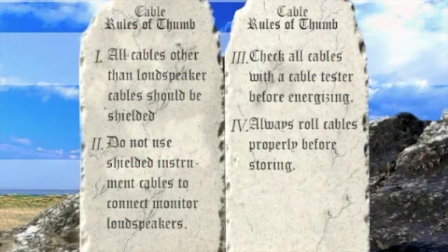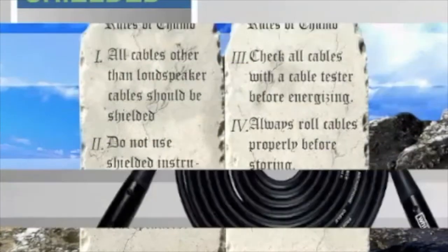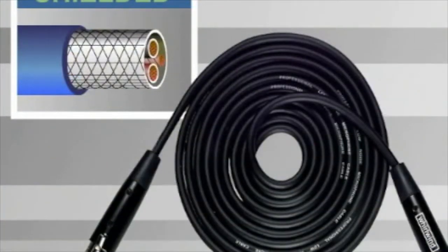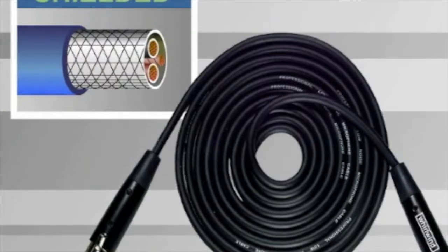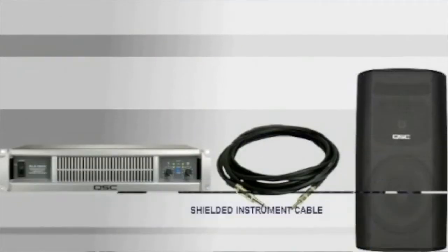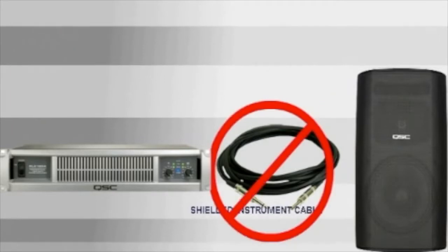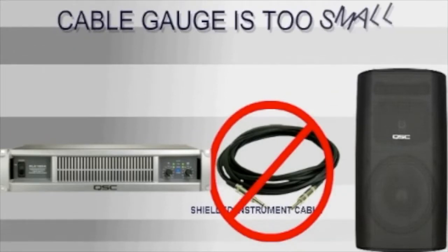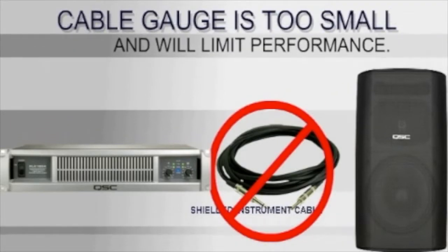Here are a few cable rules of thumb. All cables, other than loudspeaker cables, should be shielded. Do not use shielded instrument cables to connect monitor loudspeakers. The cable gauge is too small and will limit performance.